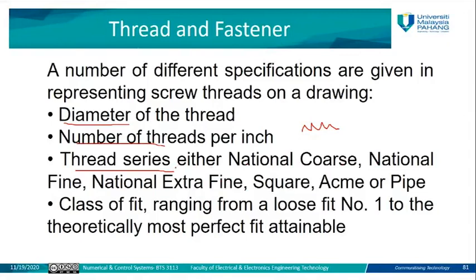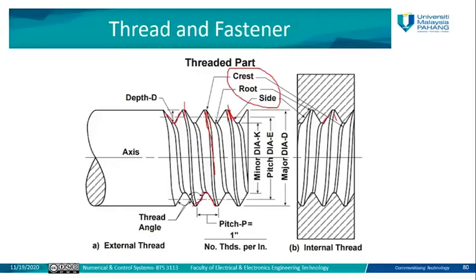They need to define also the class of fit for the allowance, for example. It's to achieve a finished product. The finished product means without any extra piece on this part, without any error in these dimensions between the thread or between the steps of the thread here, with the angle of this thread and so on.